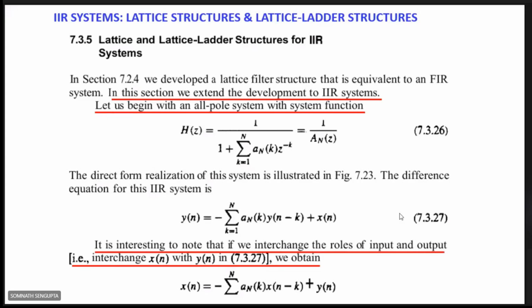Now if you multiply the left hand side and right hand side across the equation, then Y(z) will be multiplied with z to the power minus k. So in z domain, it is multiplied with z to the power minus k. So in time domain, it will be y of n minus k. And X(z) inverse z transform is x of n. So this is the equation.